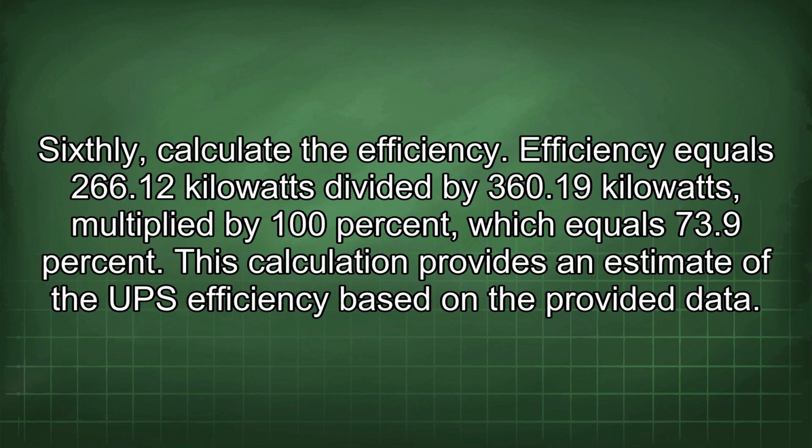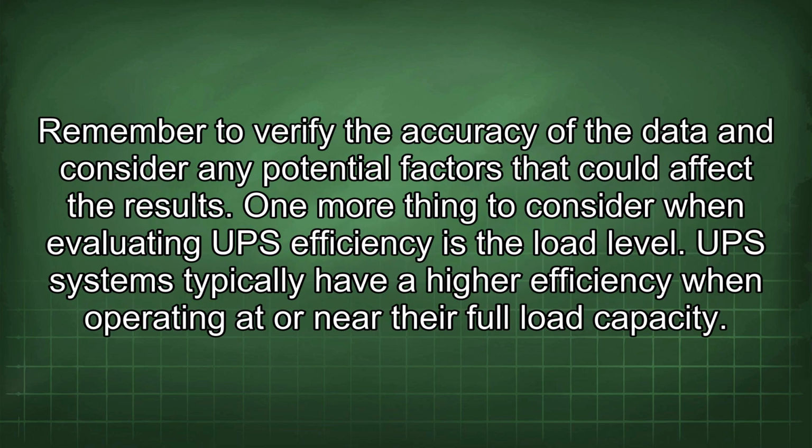This calculation provides an estimate of the UPS efficiency based on the provided data. Remember to verify the accuracy of the data and consider any potential factors that could affect the results. One more thing to consider when evaluating UPS efficiency is the load level. UPS systems typically have a higher efficiency when operating at or near their full load capacity.